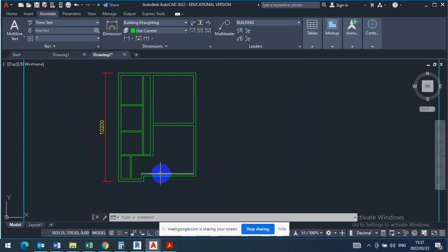Garage is 6,000 by 3,000. Inside, when we're measuring, it's inside to inside. Those are the standard sizes you must know. So there is a PDF drawing or a document I'm going to post today about the standard room sizes, so that every time you are designing, think about the standards. Don't just go out and design, or make a room too big, don't go beyond what is in the South African building regulations.